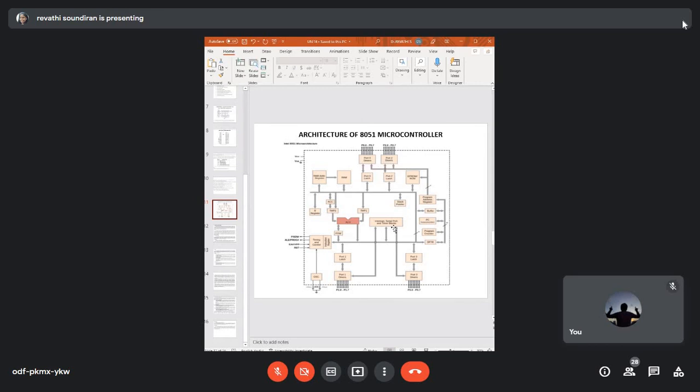You can have interrupts from your serial port during transmission and reception of data, interrupts from timer operation when an overflow occurs, or internal interrupts. Interrupts can be enabled or disabled, and selected based on priority with the help of the interrupt enable register and interrupt priority register.